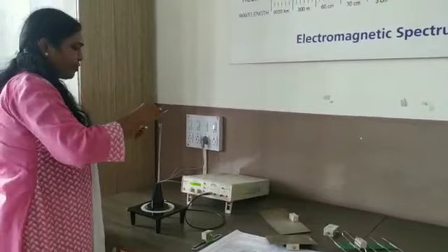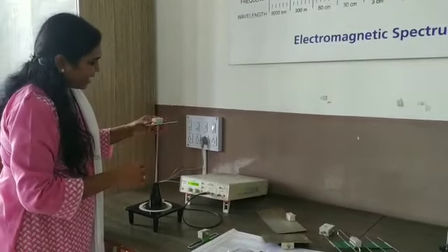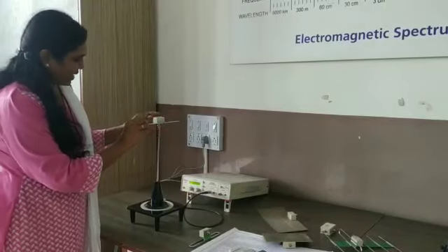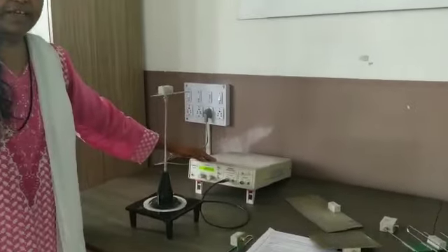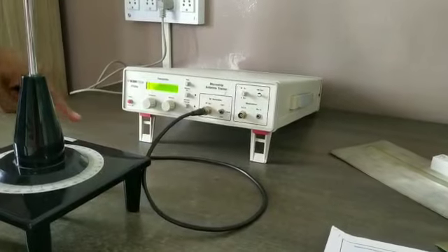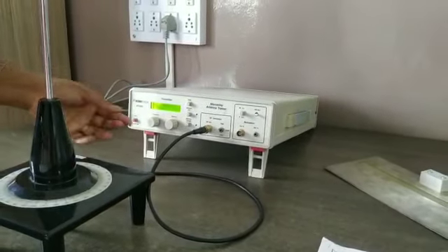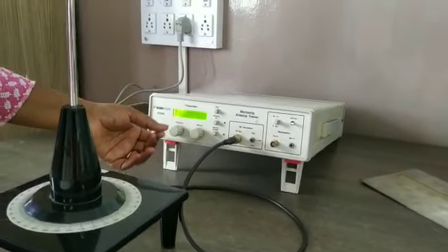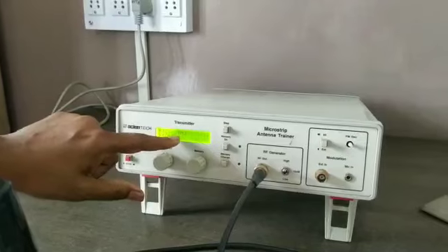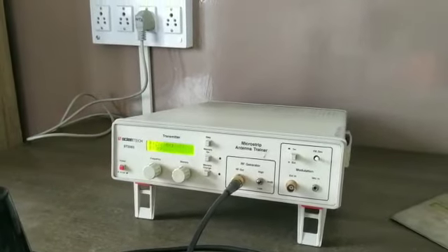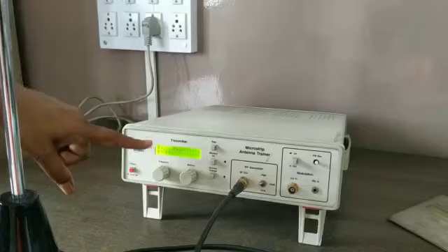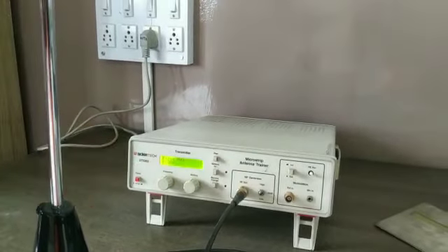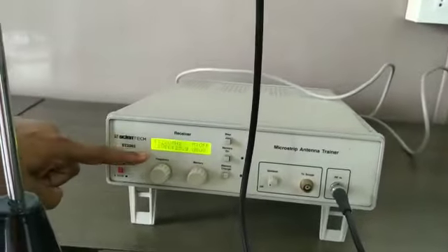Now we are going to see how to calculate the different antenna parameters for the simple dipole antenna. Here you can see this is a transmitter to transmit the electromagnetic energy. This transmitter is connected to this antenna, and here I have set the transmission frequency to 700 megahertz. Why 700 megahertz? Because all our antennas are designed for 700 megahertz. Therefore, for the transmitter, the frequency should be 700 megahertz, as well as at the receiver, the frequency is also 700 megahertz.